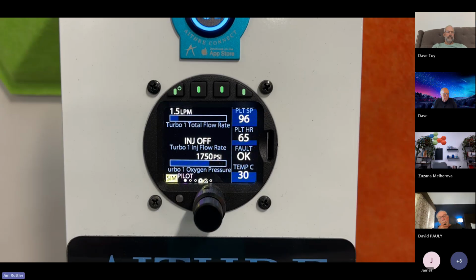Now, the Aithre Connect app is no longer required because the ATD does more or equivalent to the functions of the Aithre Connect app. However, the Aithre Connect app, if open, reinforces and acts as a relay of the data from the Lyrian, the Shield, and the Metis. The BLE data is pretty reliable, but the Aithre Connect app has a better antenna through the phone, and it will pick up the data more reliably and then relay that over to the HealthView 2 data bridge.